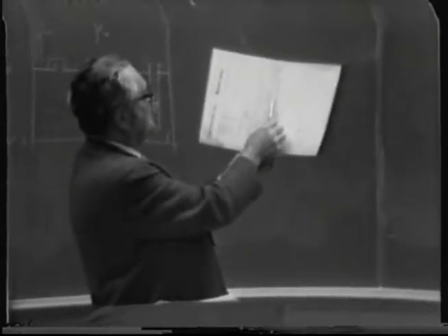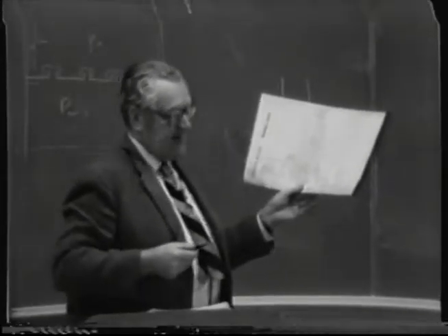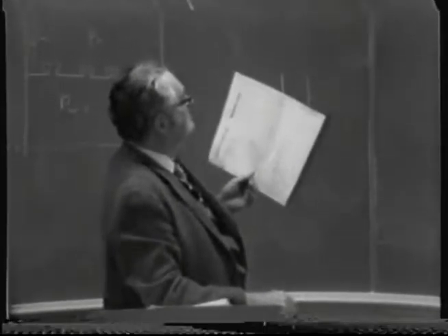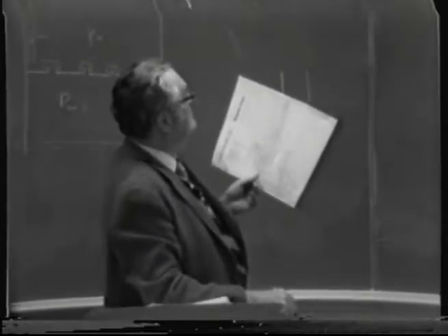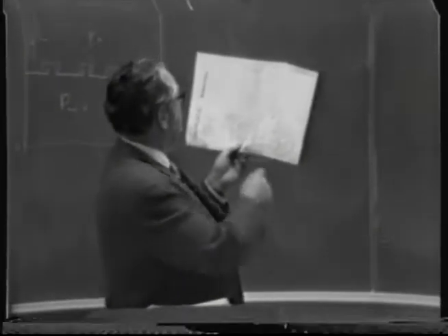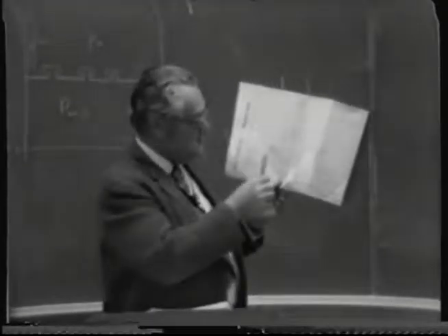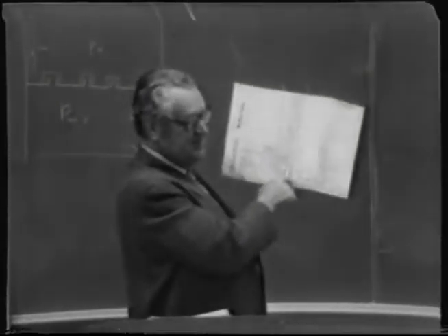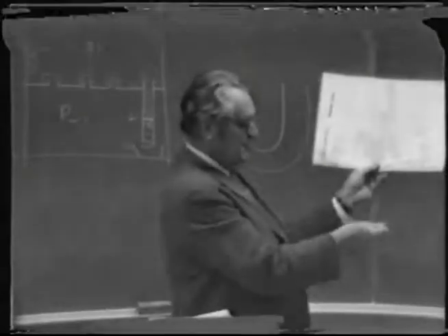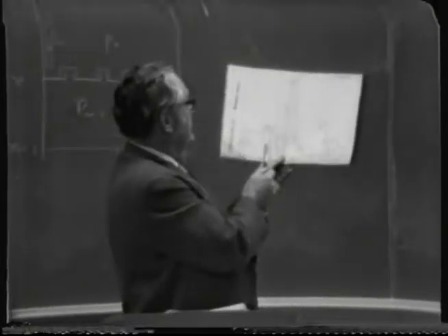The rectifying column on the top of it here appears to be about 8.5 feet in diameter if it's drawn to scale, and looks like about 70 plates in it, 70 trays in the stripping section, and 20 trays in the rectifying section. But anyway, one interesting feature about it is a preheating method. It's a preheater, which is located over here.